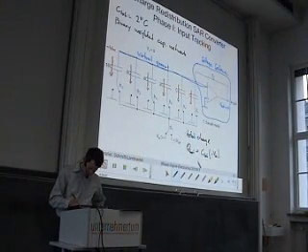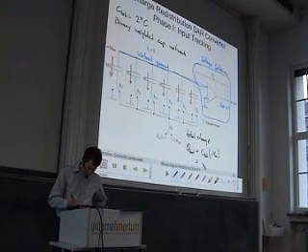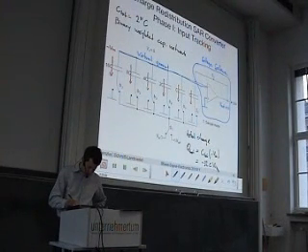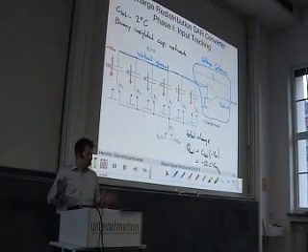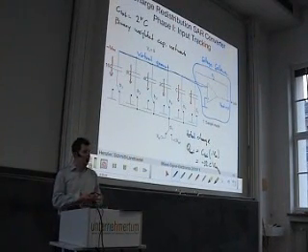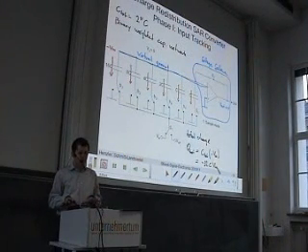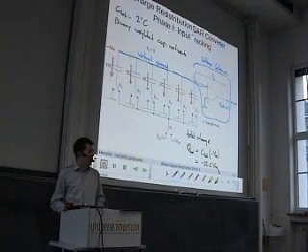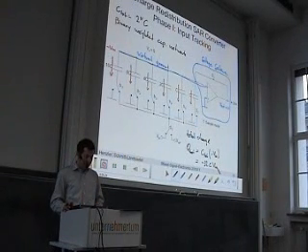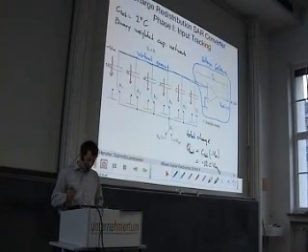Or in our example here, we have 2 to the power of n times C, which is 32 C times V in. Okay, this is the starting point of the conversion. We sample the input signal on all these capacitors. The voltage is inverted, seen as a voltage drop across these caps. All caps lie in parallel, the output signal is 0, and that's it. So we are prepared for the conversion here.